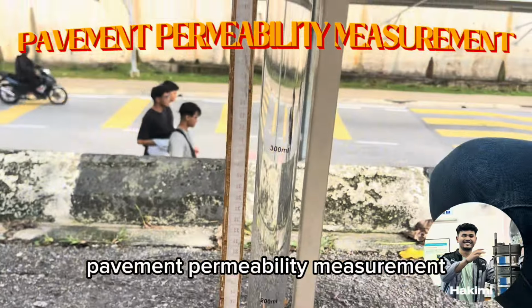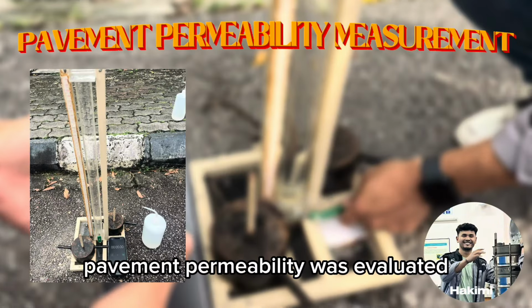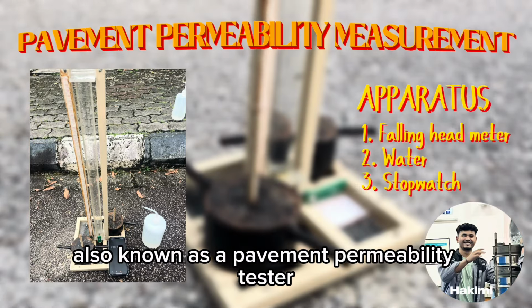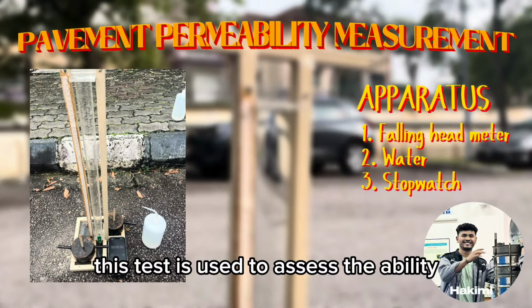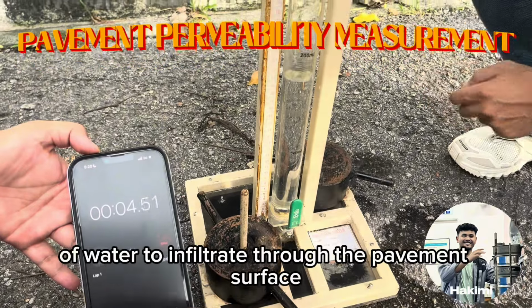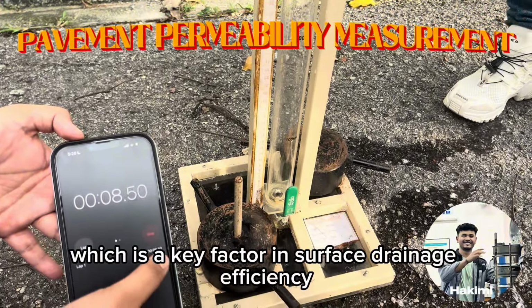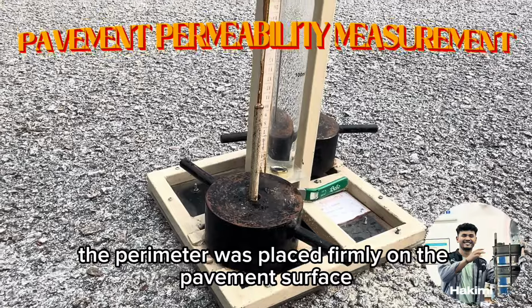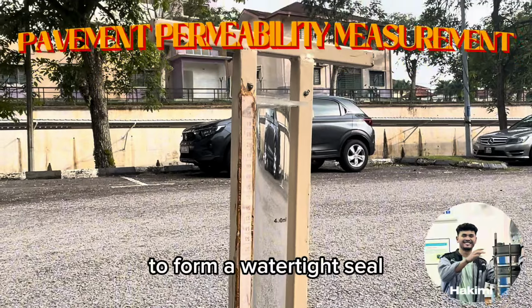Pavement permeability measurement. In addition to visual inspection, pavement permeability was evaluated using a falling head permeameter, also known as a pavement permeability tester. This test is used to assess the ability of water to infiltrate through the pavement surface, which is a key factor in surface drainage efficiency. The permeameter was placed firmly on the pavement surface to form a watertight seal.